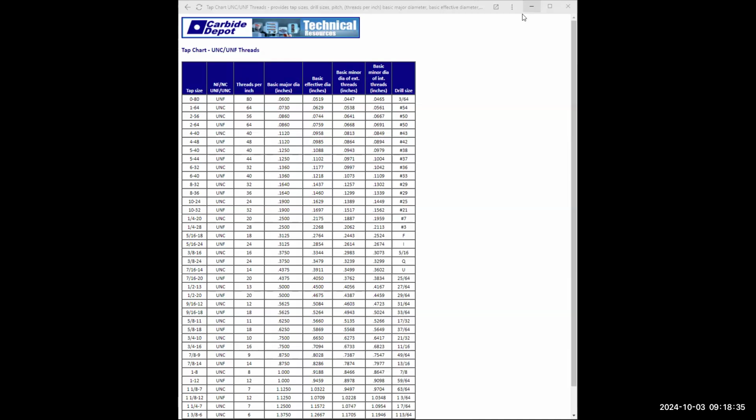We got 3 more holes to do. And we'll go type in leader. Enter. Type in near. Enter. Click on that edge. Hit F8, right? Look. I don't want to go all the way up here. I'm going to run out of space. I'm going to go about right here. Click. Turn on F8 again just for a second.